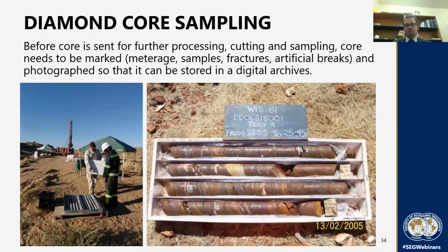I had several occasions in the past where I had to go back to the drill photograph archive in order to figure out a number of problems that we identified later on in the drilling. Such, for example, artificial breaks. Artificial breaks are introduced when people start hammering the rock. That can be both geologists and drillers.